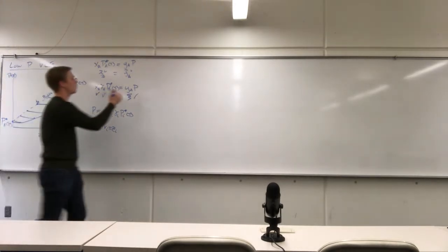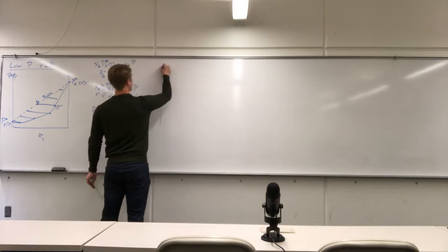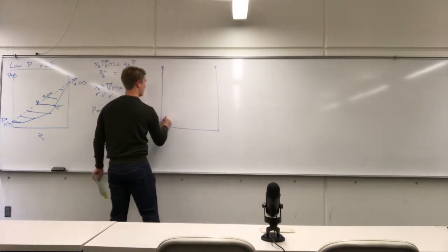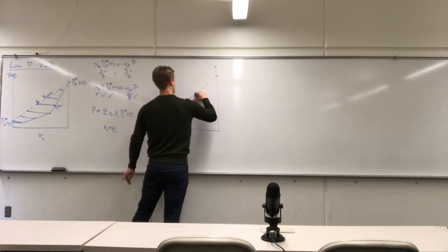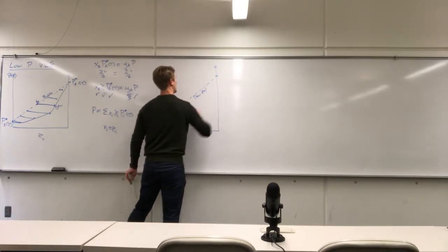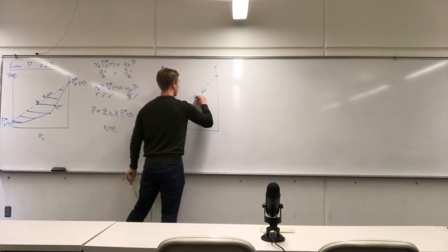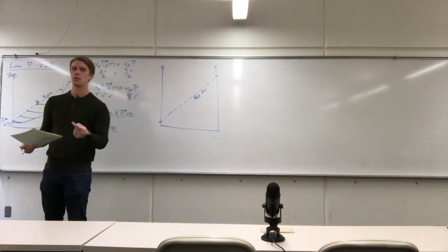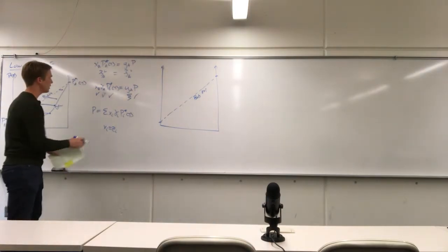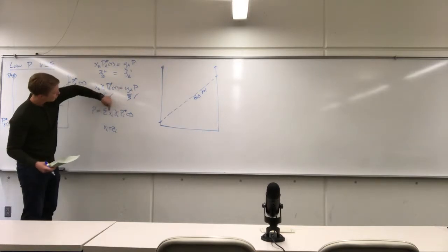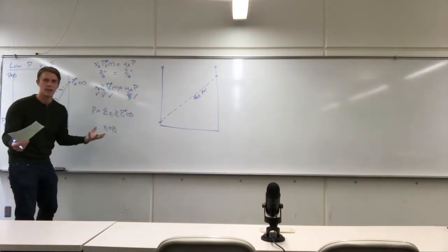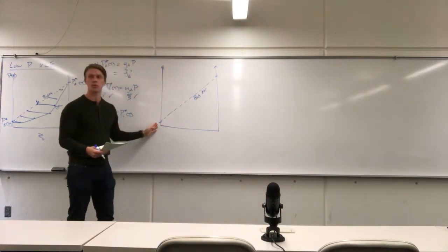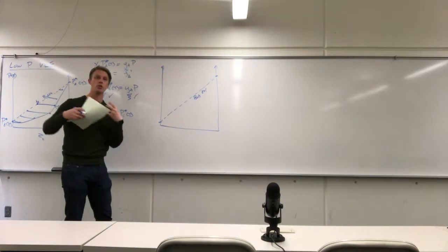So what we talked about on Wednesday was looking at non-ideal vapor-liquid equilibrium, and the non-ideality is on the liquid phase. So in this case here, we have a bubble curve where the activity coefficient is equal to 1. That means it's a weighted average. In this case here, we get rid of this here. Mole fraction times the vapor pressure, that's just a weighted average. So it should be a straight line connecting the vapor pressure of pure A to the vapor pressure of pure B. Now if the fluids don't like each other,